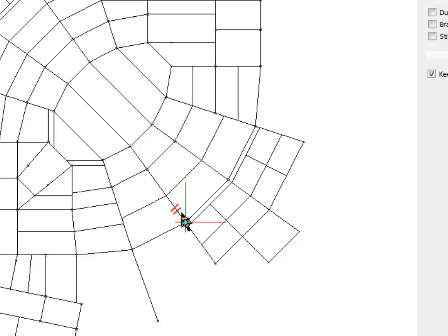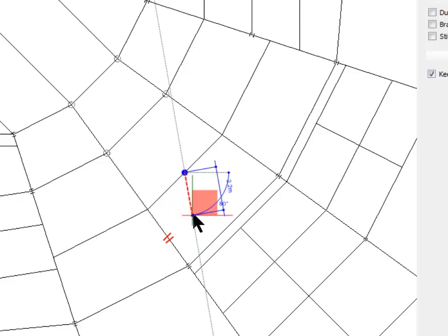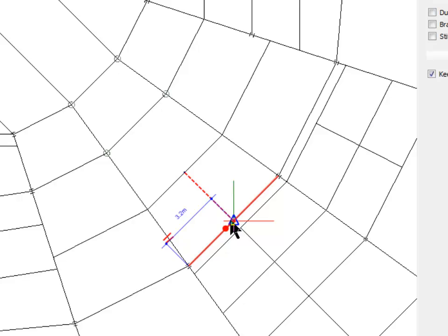So editing frames is just so beautiful. We don't need construction lines. We just draw, is the simple answer. And we can draw things parallel to each other so easily. As you saw, I want to draw, and I zoom in here, and I want to take a member, say, at midpoint, and then I want to make it parallel to this. So there we go. I've now got it parallel, and it's now parallel to that member. So drawing members has never been easier.